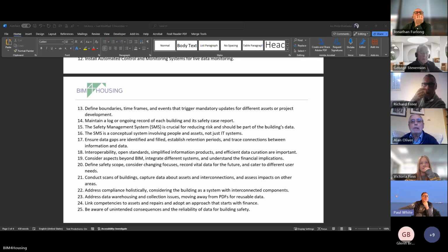Paul. The only thing that I would potentially, well, there's 2 points I want to make, but the first one is on the fire doors. If they're very old, then have a look and see what legislation or guidance was in place at the time, because you only have to actually meet the legislation of when the building was constructed. So if the legislation was in place at the time that said you could do this, then you're absolutely fine. Now, there might be other reasons why they might be unsound, but if they met the requirements at the time the building was built, then you don't have to change anything.